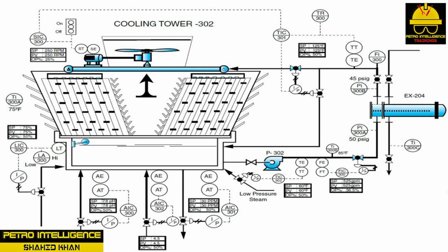Concentration cycles in the cooling tower typically can range from 3 to 7. The cooling tower is typically set at 6 concentration cycles before it blows down the system. A cycle describes one pass from the cooling tower to the process and back to the cooling tower. Cycles of concentration display the accumulation of dissolved minerals in the recirculation system. A cell is the smallest subdivision of a cooling tower that can function as an independent unit.